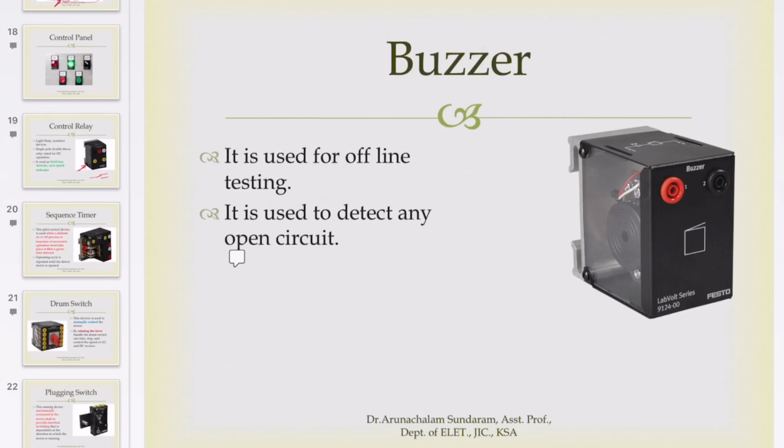This test buzzer is an audible device used by electricians to identify wires and terminals that are directly interconnected. It determines whether switch contacts are open or closed, or whether wiring is short-circuited. Unlike an ohmmeter, the buzzer will not indicate circuit continuity if any appreciable resistance is present.